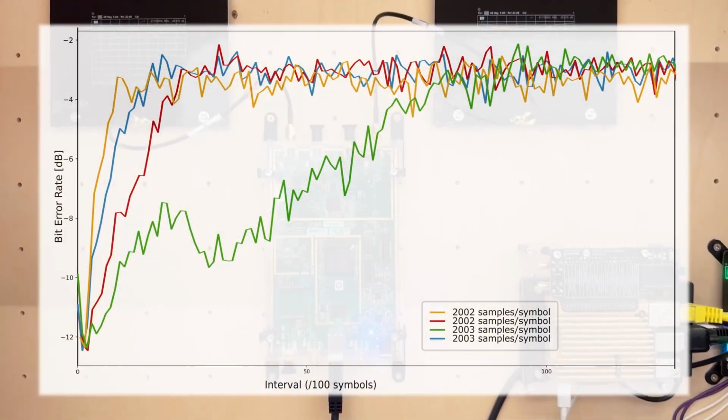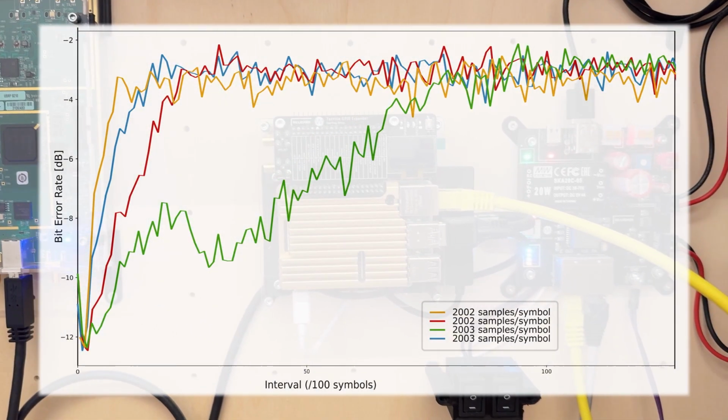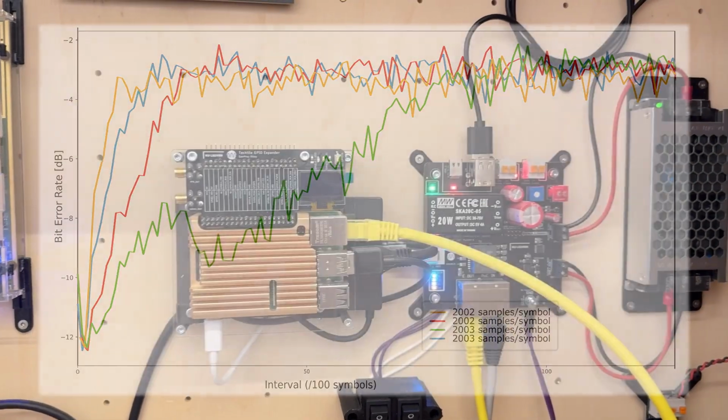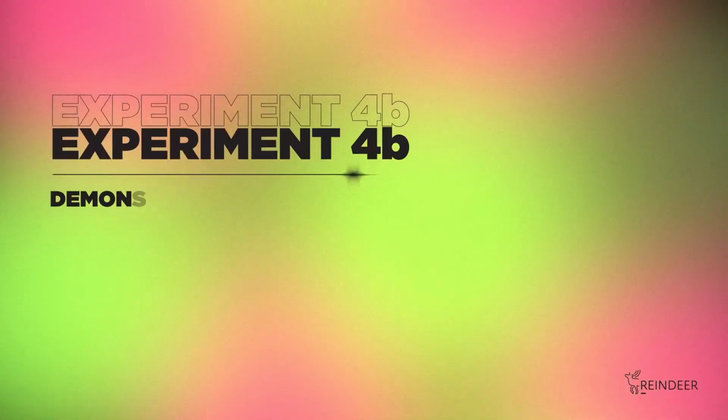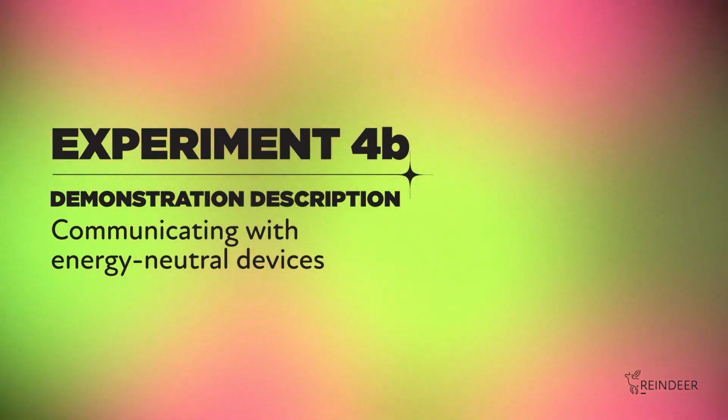Bit error rate testing shows that this non-coherent on-off keying demodulation technique is very susceptible to errors in the sample and data transmission rate, and that there is clock wandering due to the microcontroller local oscillator. Timing error detectors such as Early Late and Gardner could potentially recover the clock and improve symbol synchronization, lowering the bit error rate drastically.